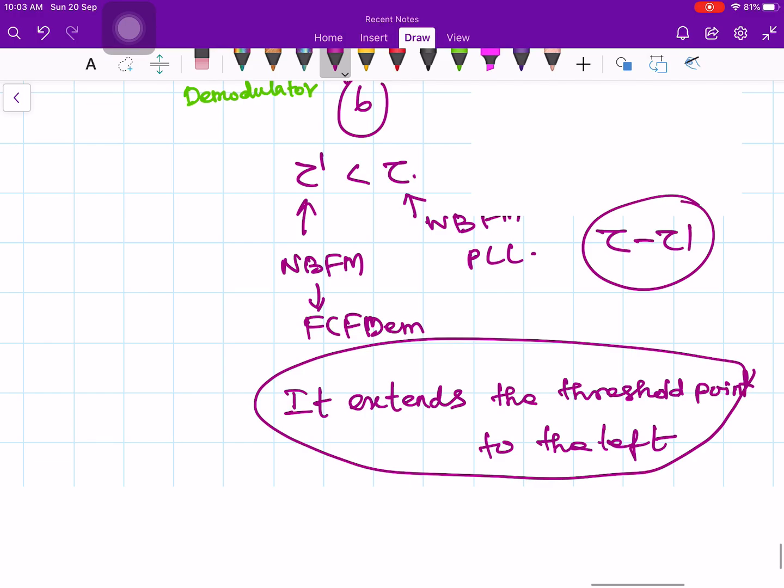So both the PLL and the frequency compressive feedback system essentially help us to do this. So we need to have PLL as well as discriminator, but the only difference is instead of using a low pass filter, here we used a band pass filter, and your voltage controlled oscillator produces the frequency of omega c minus omega naught, but in PLL it produces omega c. Okay, so I think that this brings us to the end of discussion of FM demodulation using feedback circuits. So we discussed two feedback circuits. The first one is phase locked loop, and the second one is the frequency compressive feedback. So both have similar working principles, but they differ in detail. So that's what we have discussed now.